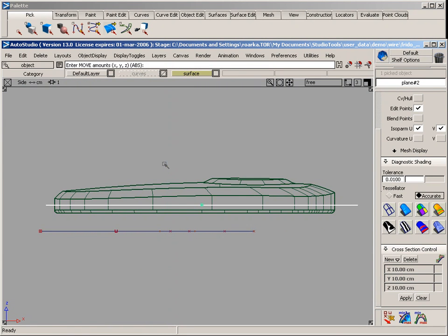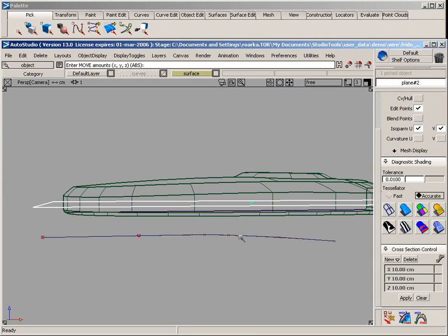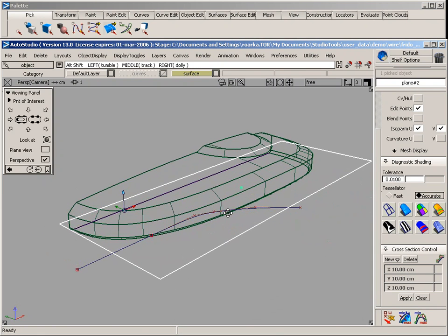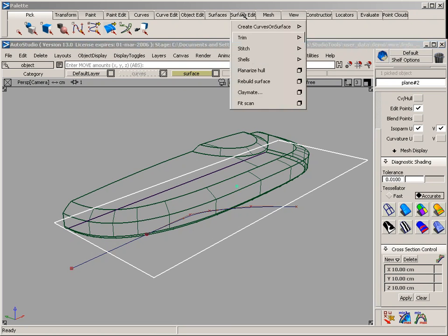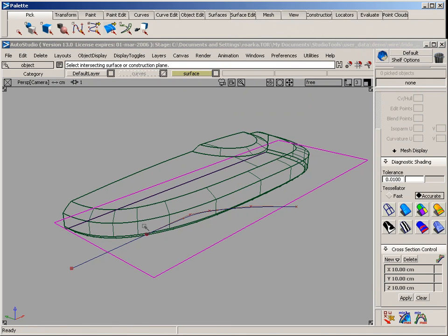Now for part lines, remember that there were a few different options that you have available for part lines. What I could do is, if this is a real product, I could use this surface plane to start and create two separate parts for both the top and the bottom one. However, for this, it's for visual representation only. I'm just going to use this plane to intersect with the side surface. I could have also projected this one on there.